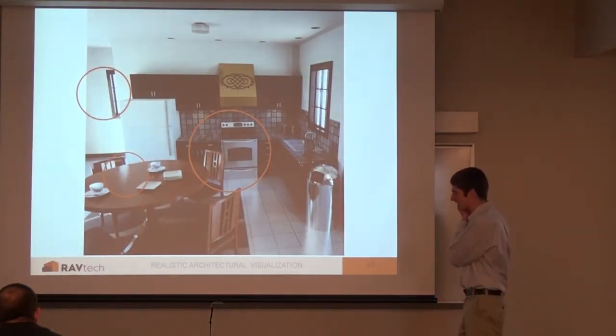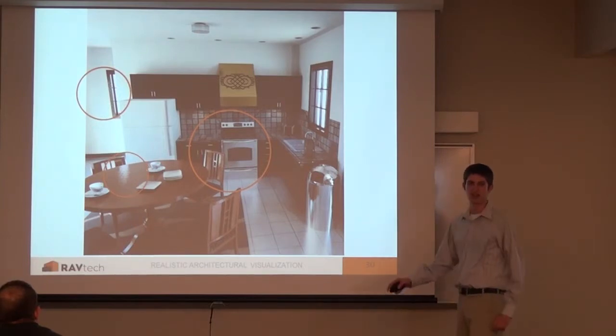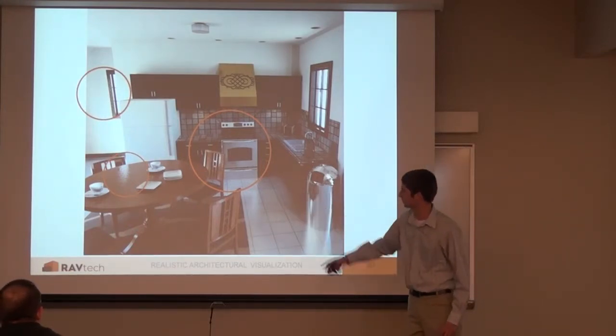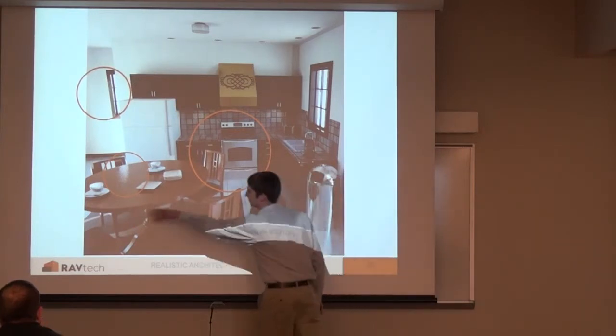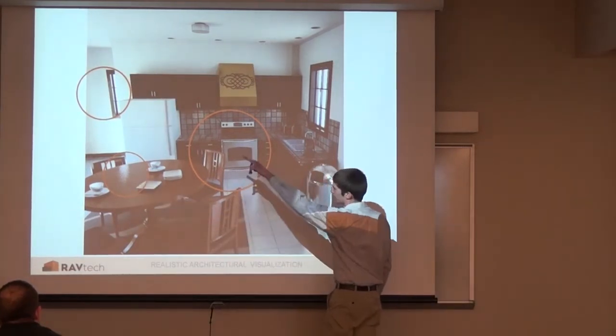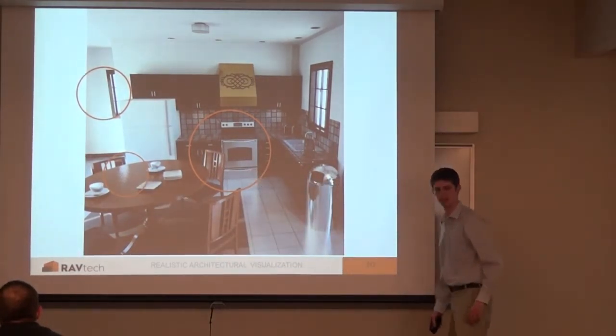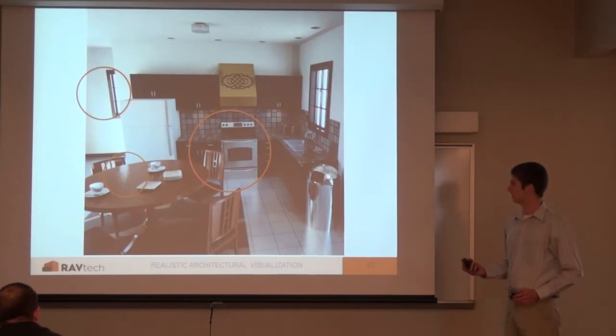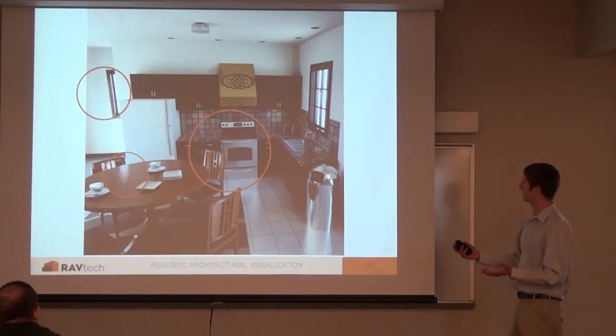All right, so as we've been saying earlier with photo editing after you render stuff, this kitchen I rendered took, I'd say, about an hour, hour and a half to do. And at first glance it turned out all right, but if you can see in these orange rings there, you've got sort of noisy pixels coming in on the table, on that window, right in front of the oven there. Not really sure why this happens, but you could go back and mess with your settings. Maybe you can re-render it, maybe it'll clear it up, maybe it won't. That's just going to be more time.